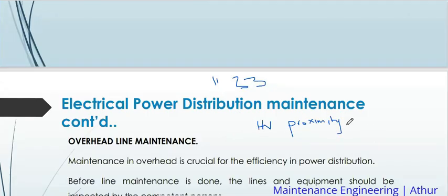That device is put on what we call an operating stick and raised up to the line. When it makes noise, it means power is still in the line. But when it doesn't, then it means the guy has put off power, and therefore you can start working.